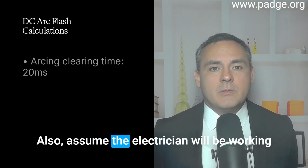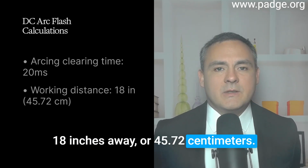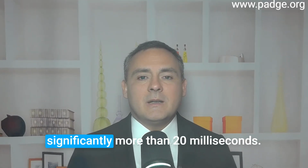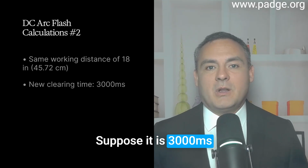Also, assume the electrician will be working 18 inches away, or 45.72 centimeters. These are the values that were plugged into the Annex D5 equation, and the result is 4.78 calories per centimeter squared. Now, assume the clearing time is significantly more than 20 milliseconds. Suppose it is 3,000 milliseconds.